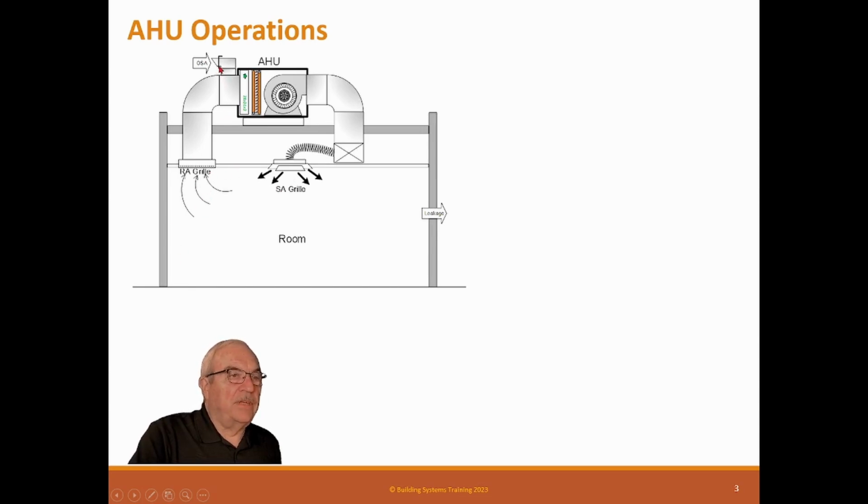And then the other thing here is a fresh air inlet. Because the fan is sucking the air this way and blowing the air this way, this is all under negative pressure. So if you put a damper here to the outside, it will suck outside air in. As a balance contractor, it's important for us to set up outside air so that this space is slightly under positive pressure. And the reason for that is all buildings leak air. It's impossible to build a totally tight building. So we want to produce enough outside air to cover up those leaks. So this is positive pressure.